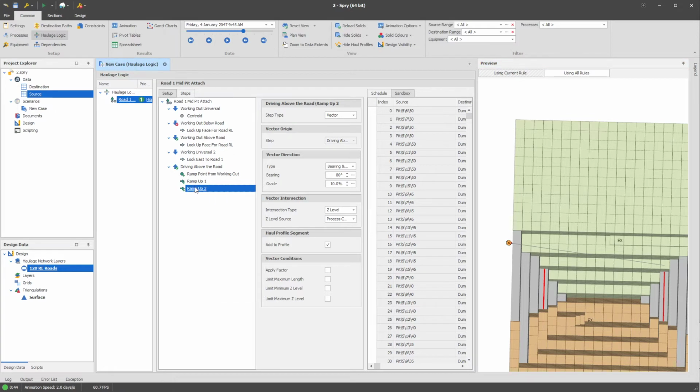And actually, the thing that I missed here, as I said, I didn't do a rehearsal, is this should have a distance limit on it. So let's put in a distance limit of, let's say, 500 meters, maybe even to drive home how this is going to work. We might go 300. So we'll go with a 300 meter maximum length, and then I start inserting copies but changing the bearing, and that's all I have to do.